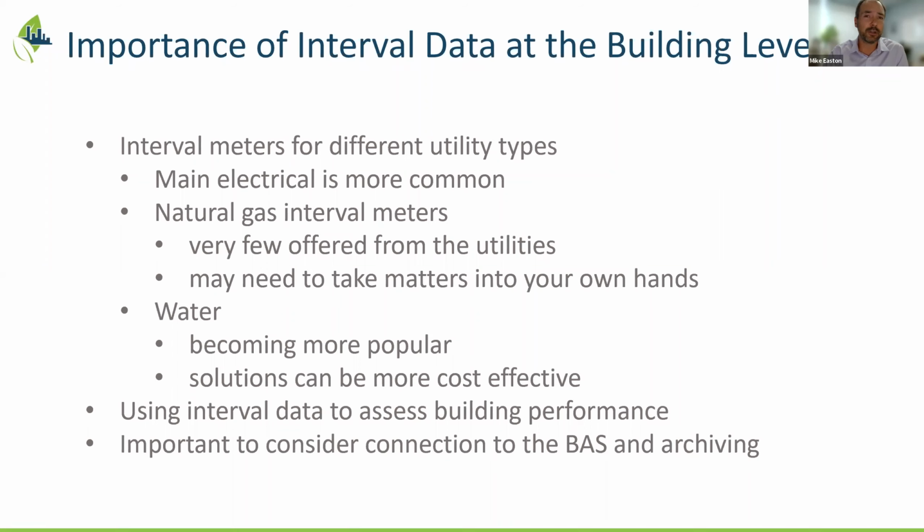And we find this upgrade usually ends up being somewhere between $3,000 and $5,000 to do, because you need the modules and some labor to get that work done. If you're in a jurisdiction where the utility does not allow their natural gas meter to be upgraded, you typically would go with a redundant meter, probably an insertion meter on a larger load. These are fairly accurate and fairly easy to install. They're not a revenue grade installation, but nonetheless, they're a good balance between cost and accuracy. And so we've been doing a lot of our redundant building level gas meters as insertion meters lately.